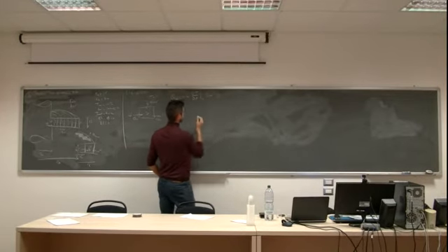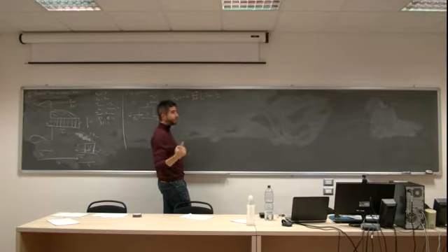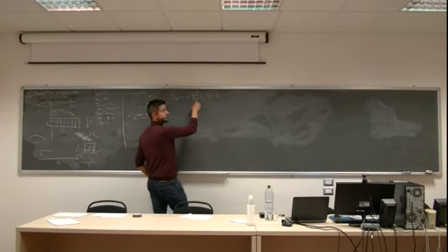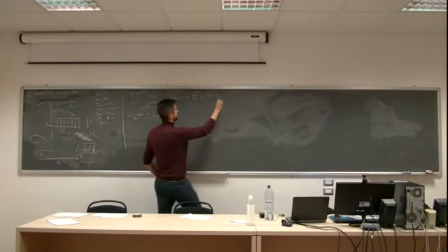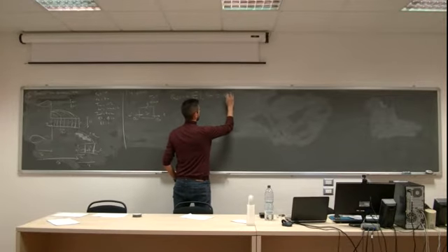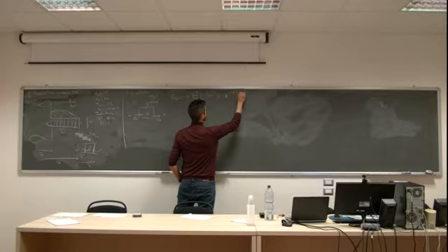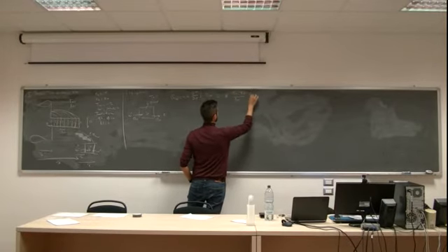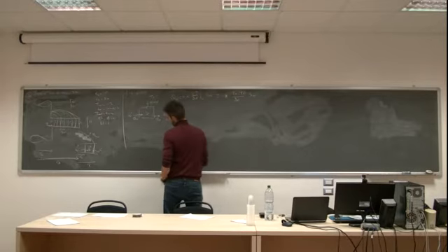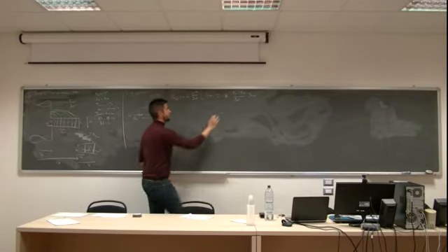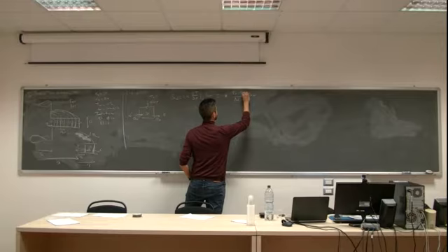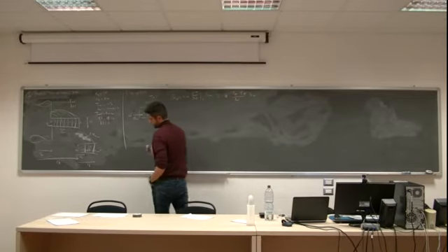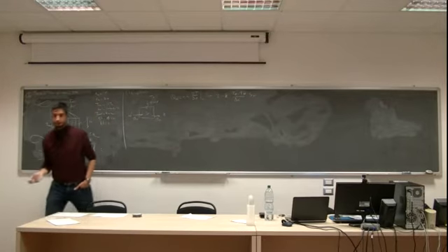This is more or less, and this is the approximation that we are going to face because we cannot solve this derivative. Minus k, (Tp minus Tw) divided by delta R, multiplied by S west. Agree with me?